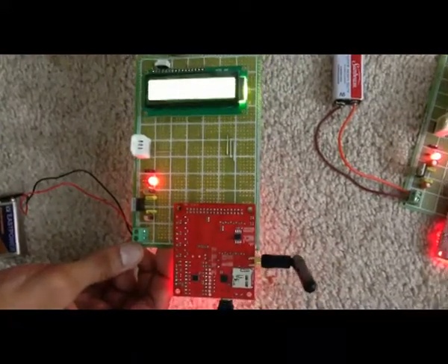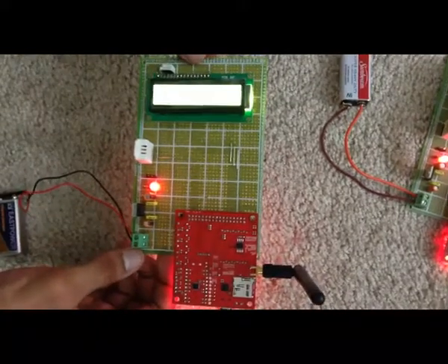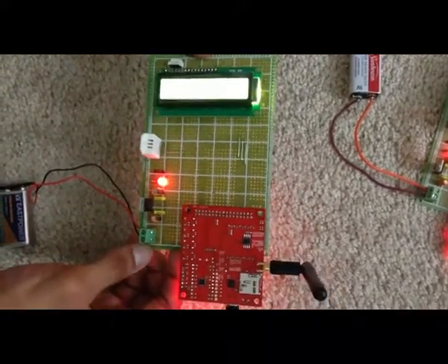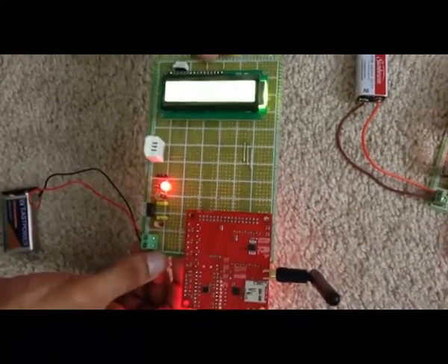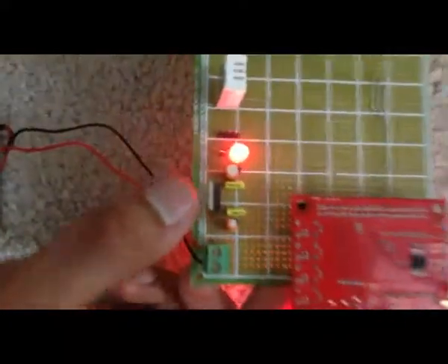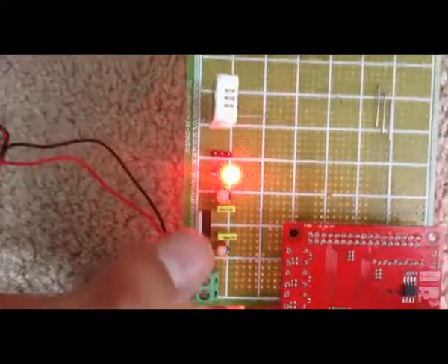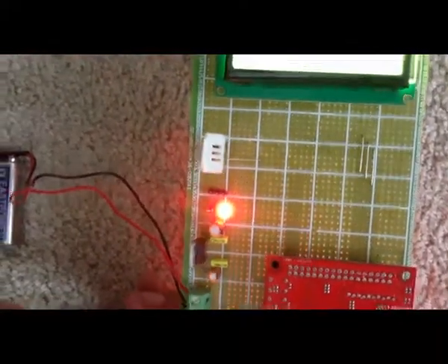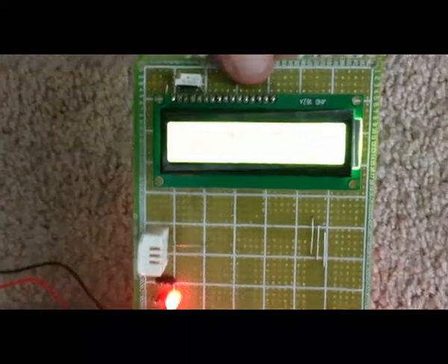Now I'll give you a basic idea of the hardware used in this project. We basically used 4 general purpose PCBs, and we just used connectors and mounted everything on it, as you can see over here. We designed a 5 volt voltage regulator using the 7805 IC. This 5 volt is used by the temperature and humidity sensor and also by this LCD.